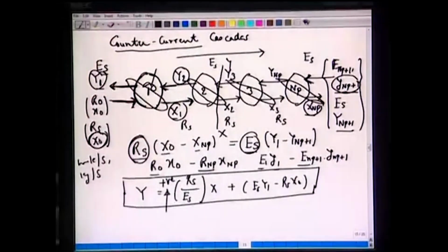So, what we noticed here, we have made a species balance for co-current, cross current and counter current cascades, very similar to the previous case where we made a species balance for co-current continuous contact process and counter current continuous contact process. The overall material balance remains the same. We have negative slopes in case of co-current or cross current, and we had a positive slope in case of counter current flow, in the counter current continuous contact process or the counter current stage wise processes. However, these are discrete: we have stage 1, stage 2, stage 3. There we had one continuous column, which is a packed bed. Although, we are getting similar mathematical expressions.